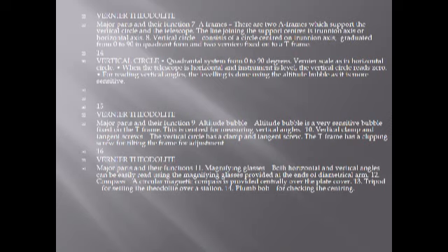The most important thing about the tripod is that we first fix it in the proper way, because if the tripod is not fixed properly, the reading is incorrect. For setting the theodolite over a station, the plumb bob is used for measuring the centering.